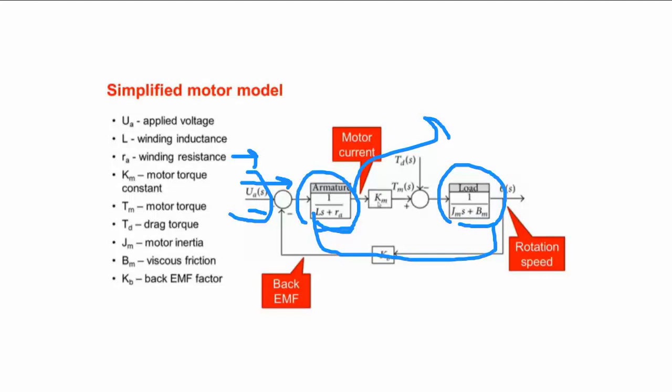For example, in incremental encoder, your motor rotates 1 RPM mechanically. Also, don't forget it, mechanical RPM and electrical RPM are different things. Okay, you remember from your electromechanical energy course, we have pole numbers. Pole numbers give us electrical rotational speed. Mechanical speed is 1 RPM of your shaft rotating. Electrical speed and mechanical speed are different things.